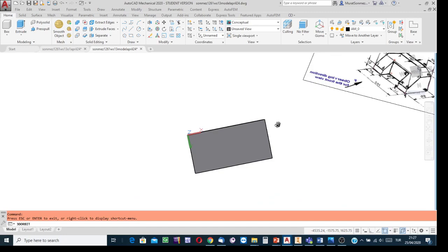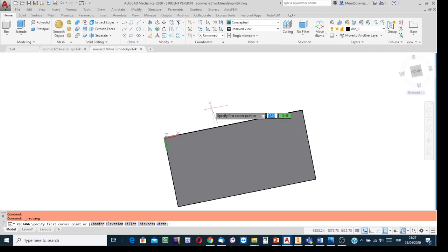So, start the rectangle creation process, and the system is asking me for the first point, the first corner along this boundary of the bottom side surface. Its abscissa is 25 relative to the origin, 25. Click the comma key, ordinate is 0. Press enter. And then I'm going to create the rectangle in this direction.